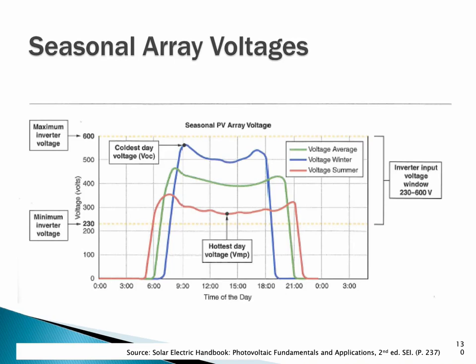At a certain point, if we lose our voltage because of heat, the inverter will shut down and then restart after it cools down, maybe in the afternoon. So we lose multiple hours of performance when the voltage sags too low.